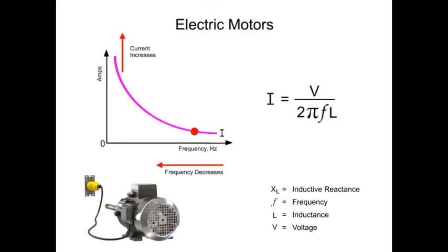Motors are frequency sensitive, which means that frequency changes can cause speed changes within the motor. If frequency decreases significantly, the motor may experience a large increase in current, which can cause motor components to overheat.